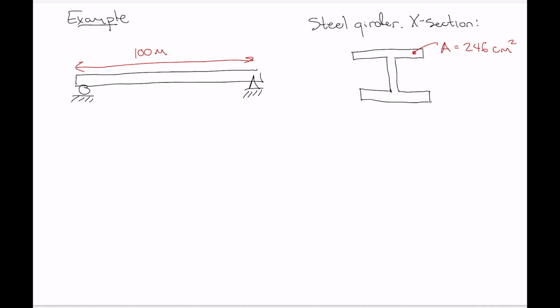Sometimes you have expansion joints with sort of rollers below to allow extension to occur. But let's say, being a young engineer, you forget to put in that roller and you pin that girder at both ends to constrain its length.